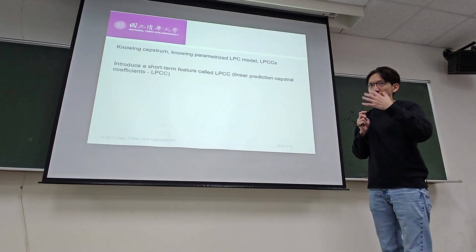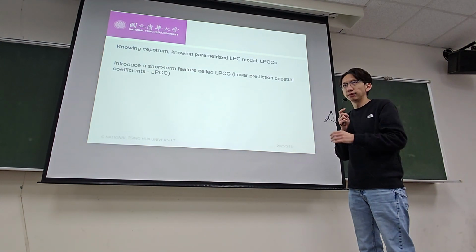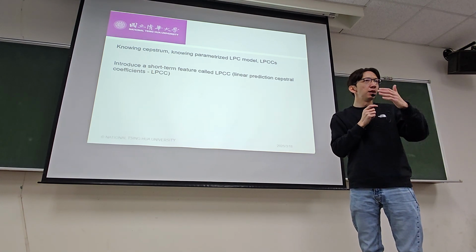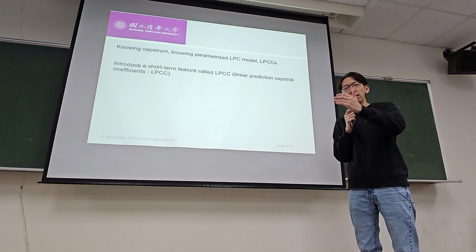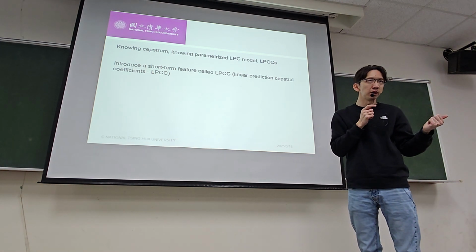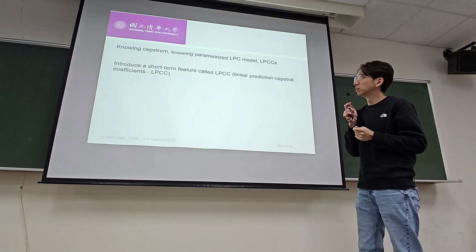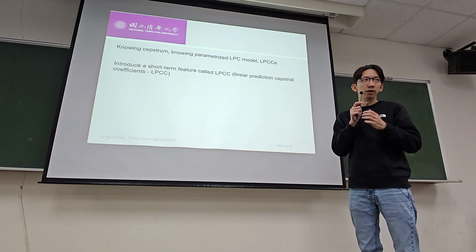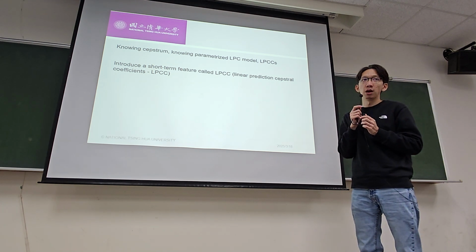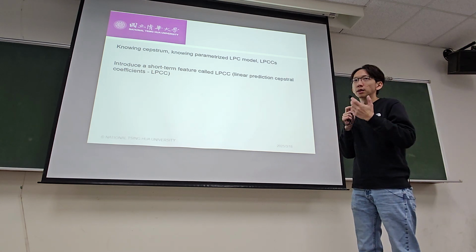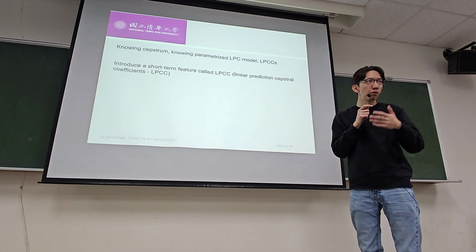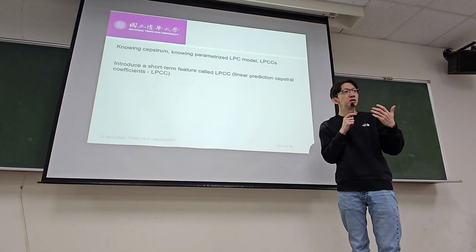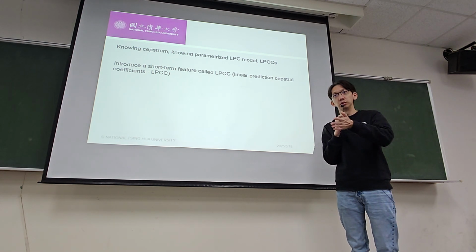That's a broad, quick dive into cepstral analysis. Think of it as a new domain that can tease apart low frequency and high frequency convolution in the original time domain, making them linearly separable. Now, knowing this cepstral domain, and having learned a parameterized model called the LPC model, we can start deriving what we call coefficients, or in machine learning terminology, features, called LPCC, linear prediction cepstral coefficients.